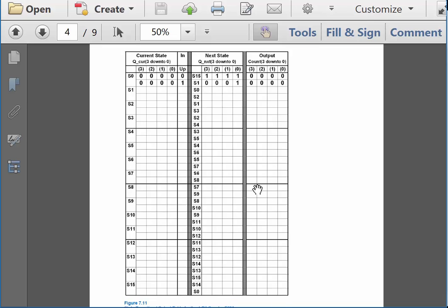And the reason this is really advantageous to do is because when we go to code up the logic for the next state, we are going to be able to do an assignment to q_next as a vector. So we're going to look at current state and in, and we'll use a conditional signal assignment, and we'll be able to assign a 4-bit vector to this. And when we do that, we are essentially creating 4 separate combinational logic circuits with 1 vector assignment. So it becomes very nice. Okay, so go ahead and fill that in.